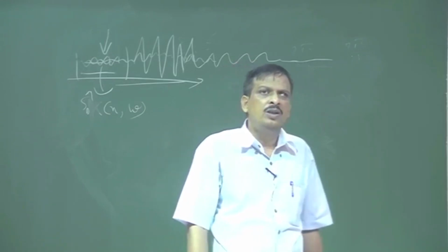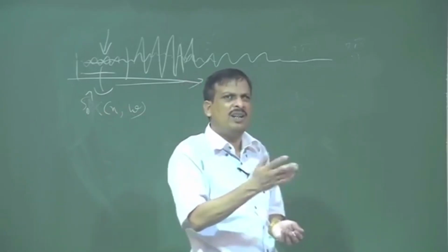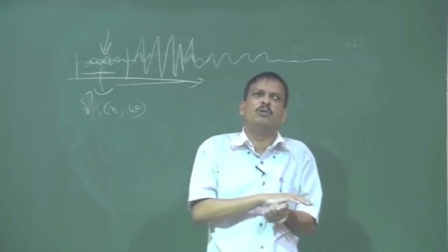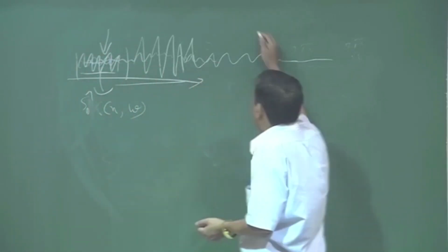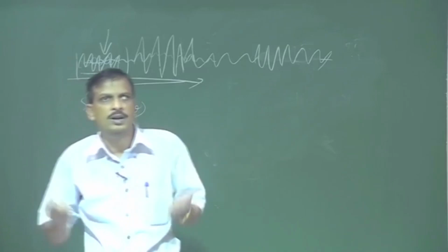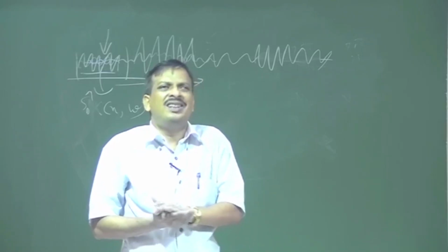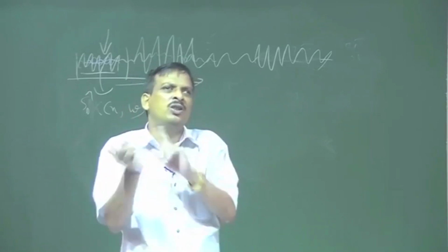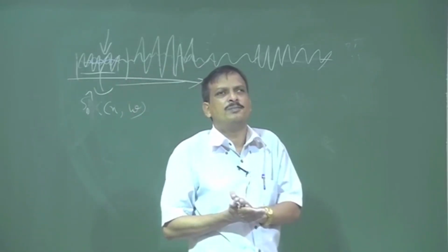Okay. So this way there are a lot of algorithms you can develop. There may be a complex procedure, I can estimate the noise in a different way, I can subtract not fully. What is the problem is that if this is noise, and the speech signal contains a sibilant sound which is also noise, if I subtract it, the sibilant sound may go. So this is the problem. So then I can say, okay, if this is a sibilant sound, then do not subtract this. Those kinds of algorithms I can write and I can remove the noise from the speech signal.